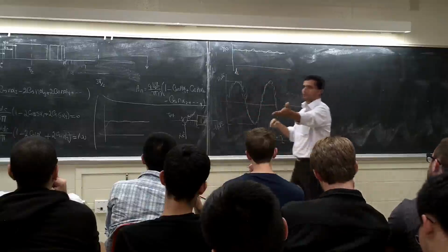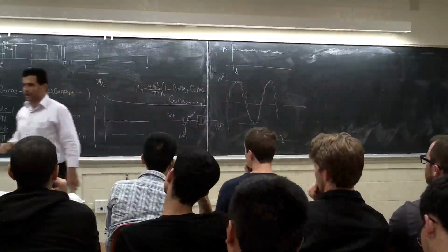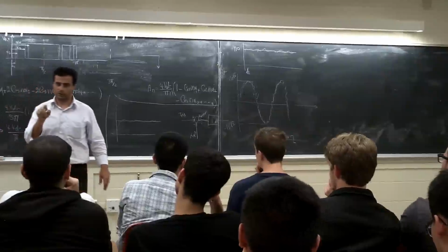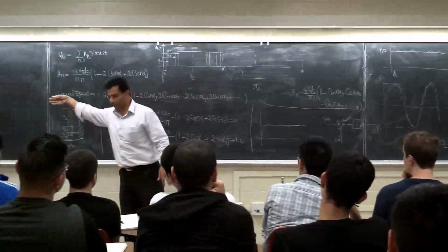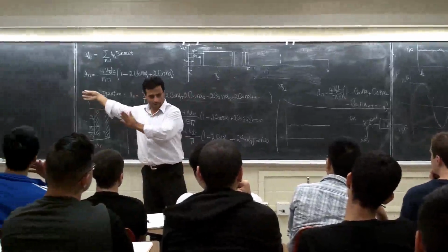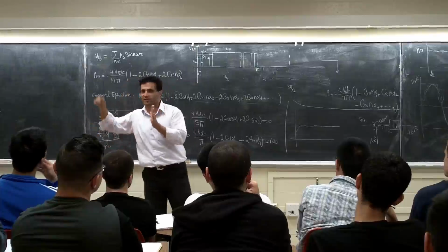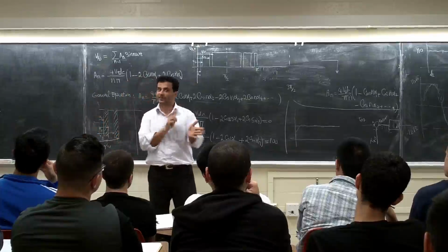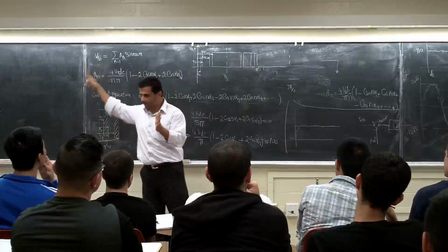Turn on the scope, connect it to the grid voltage, and don't trigger it. What is going to happen? You're going to see a sine waveform moving all the time, because that one is moving at 60 Hz. When you trigger it, you are fixing it to something, but the real voltage is moving, right?